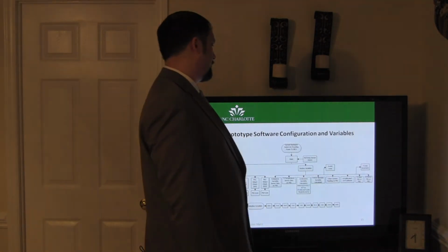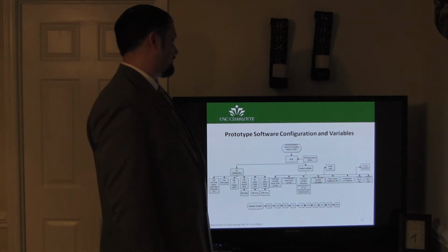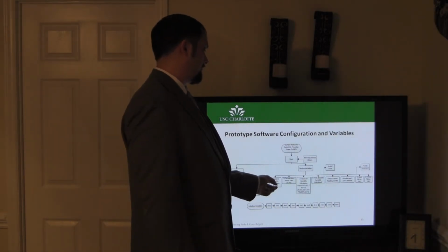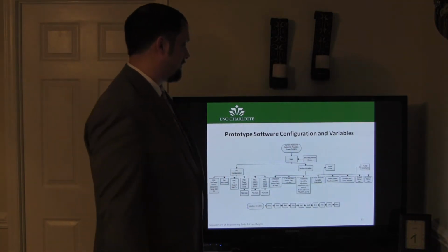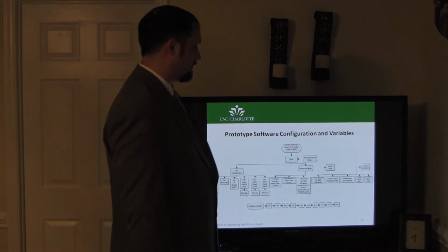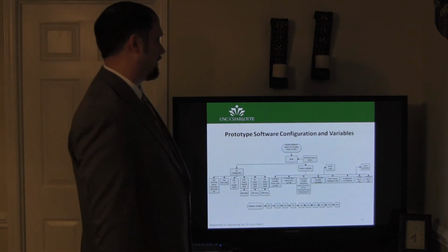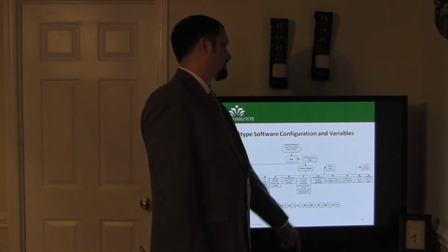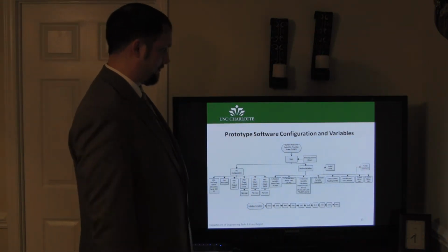Here we're declaring these variables. Relative humidity is the relative humidity data that we read from the relative humidity and temperature sensor. The T is the temperature data that we read from that same sensor. A is the absolute humidity calculation. The F is the first absolute humidity calculated that it stores. I is the raw current that it reads from the current transformer. U is the calibrated current that is read from the current transformer.